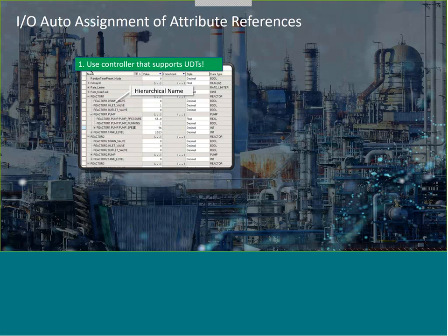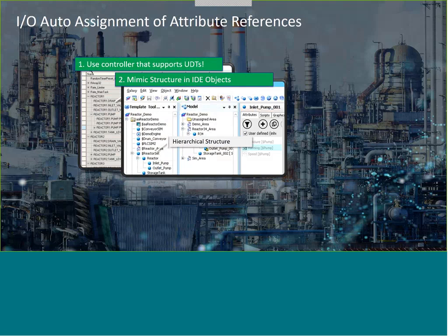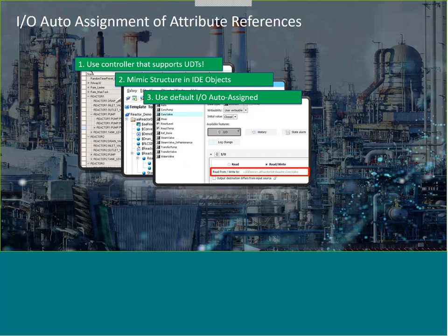So if we take the same methodology in terms of how we look at the PLCs, and we've got UDTs here, so we're engineering our PLC with UDTs. It's the same structure that we actually want inside of System Platform, as I mentioned earlier. So if we match that using the objects that we're creating from the object wizards, we then have an ability to do something called I/O auto-assignment.